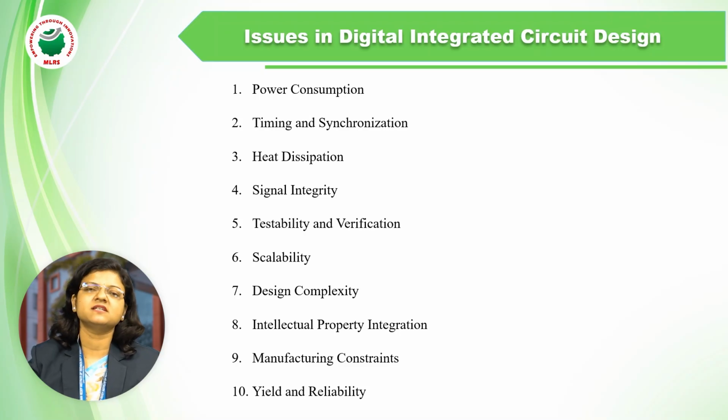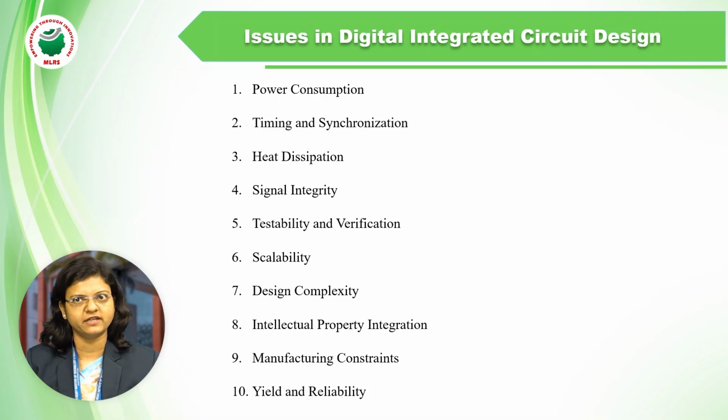ICs are often used in portable and battery powered devices, so minimizing power consumption is the main issue. To reduce it, designers need to use techniques, for example clock gating, power gating, and the third technique is dynamic voltage and frequency scaling.